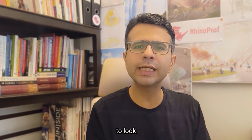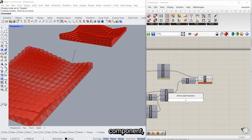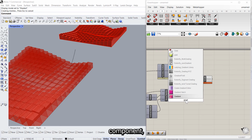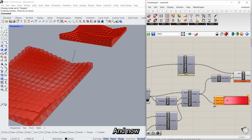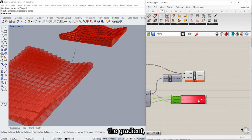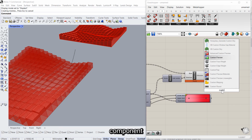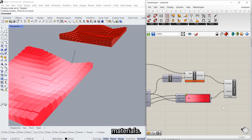Now if you want it to look more colorful, let's put a gradient component. Put the remap values as parameters, and now we'll need to define the minimum and maximum range. So pull in the minimum and maximum numbers from the remap into the gradient. Now put a custom preview component, and then we put the values of the gradient into materials.